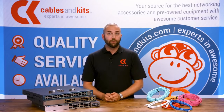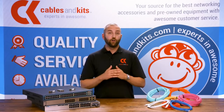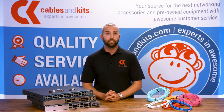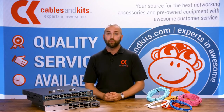So, why do you need one? Well, we have a rule of thumb here internally and kind of a guide that we give to our customers. So, if you're trying to connect two devices that's over about 6 to 7 feet, which would typically be outside of one cabinet, you likely need to look for a transceiver to facilitate that communication. So, which one do you need? Well, that depends on a couple of answers to a couple of different questions.